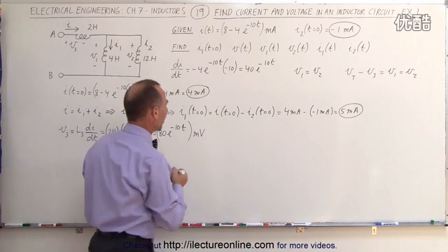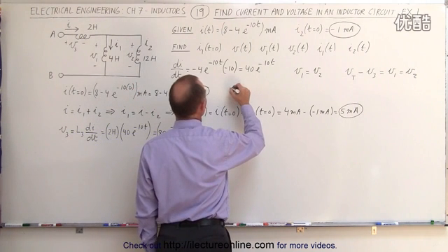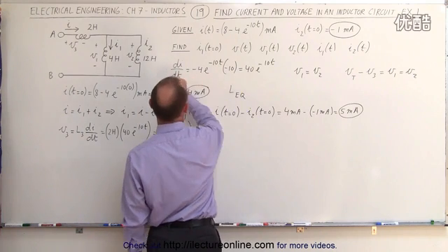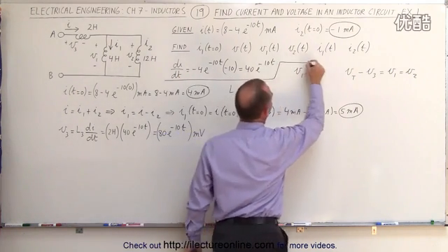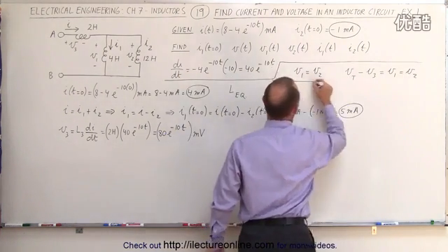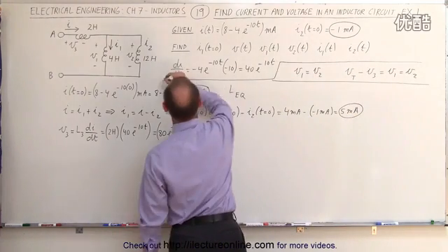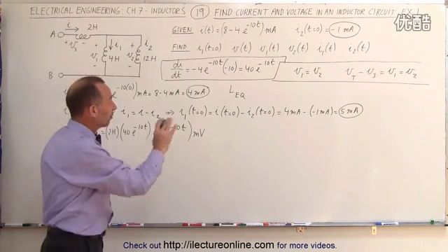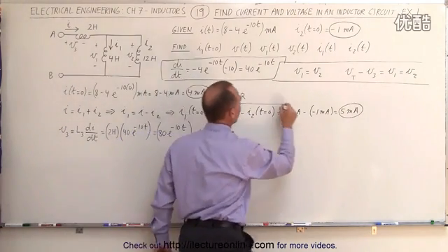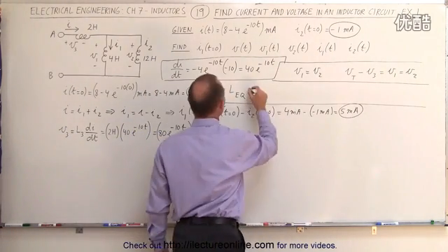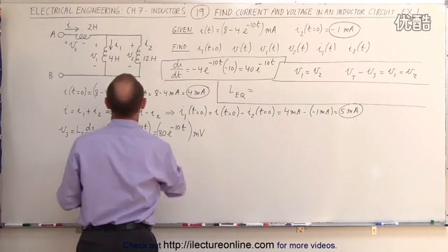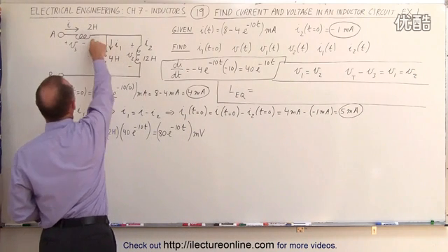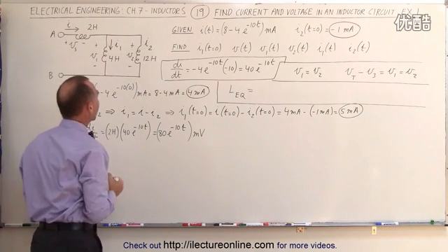So what we need to find here is L total or L equivalent. Let me draw some lines in here so we don't get too confused with all the equations on the board, because after all, there's a lot to be written here and there's only so much board space. So now I'm going to find the equivalent inductance, which means that I have to first add these two together, which are in parallel, and then add that to this one, which means they're in series here.